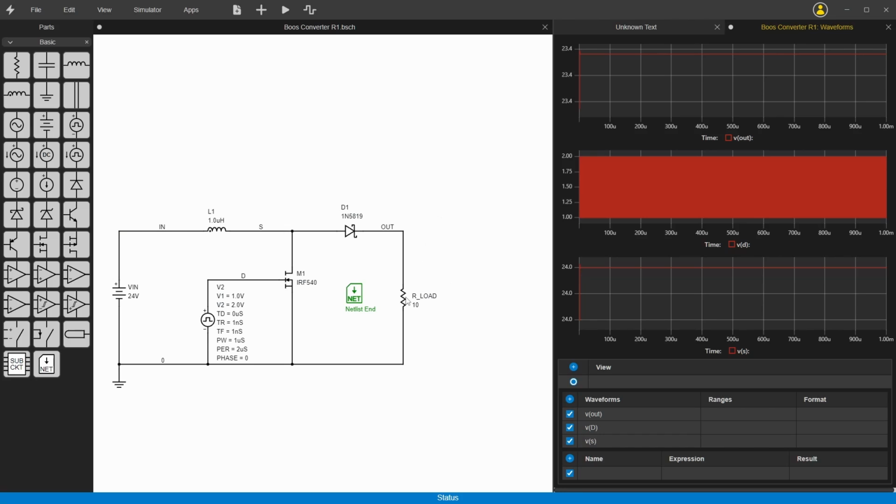Alright, so we're back here. Gonna move this over, get some more room, and put this capacitor down here. So this will be our output filter. I'm going to make that a little bit bigger, so maybe 100 micros. And we want this to have an initial condition. So in Spice, you do that with an IC statement.